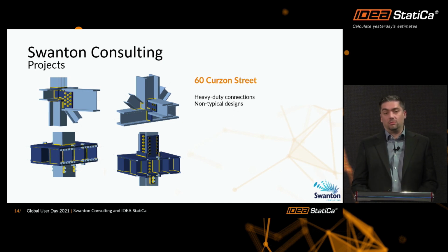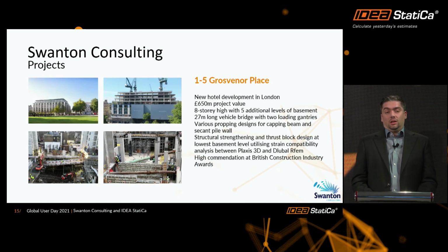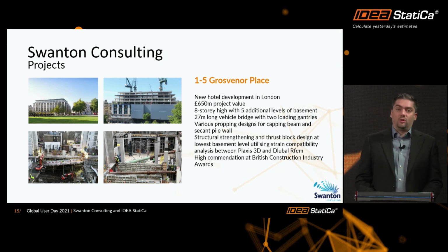The bottom two are shear keys, basically cast into reinforced concrete with reinforced concrete rebar couplers and splices incorporated into the connection area, very heavy elements, where we had a great help from IDEA StatiCa in designing and assessing all these things.